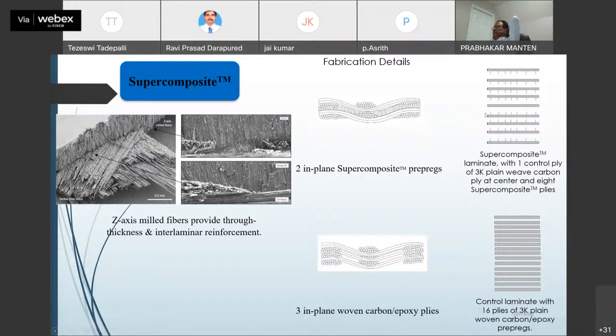So we studied some super composite laminate with a base layer, 16 plies of a pure laminate without these, and then these things grown on them. And the idea why we took so many is we wanted to not change the weight per unit; that was a requirement. So we overkilled it actually. We put a lot more than necessary.